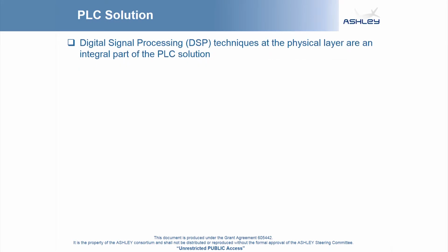Nevertheless, these challenges are nothing new for PLC technology and exist in many other application areas. PLC technology has been developed and optimized for such environmental conditions for over 15 years now. Advanced digital signal processing (DSP) techniques at the physical layer of the communications protocol are an integral part of the PLC solution and the means by which many of those problems may be mitigated.